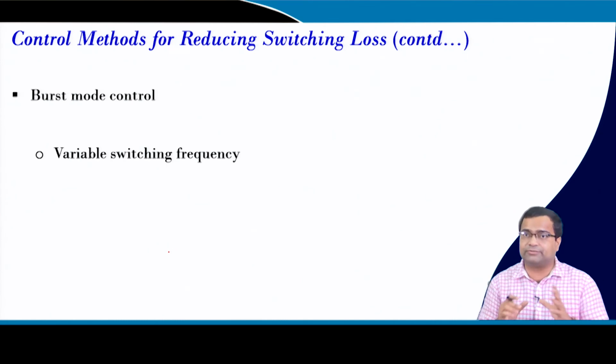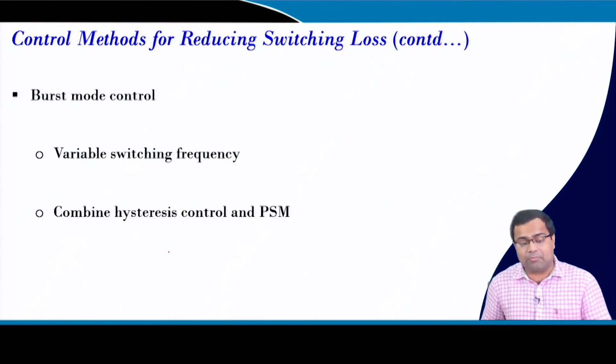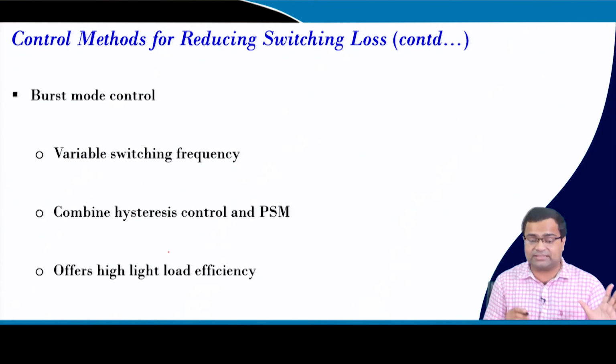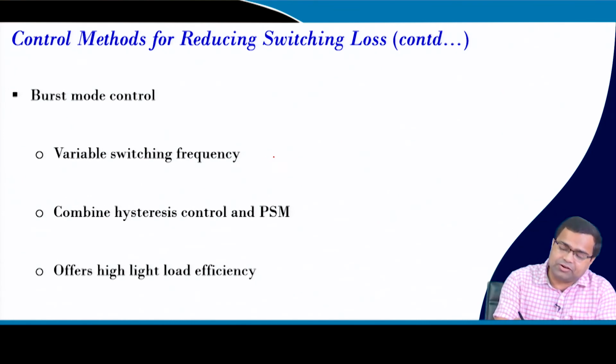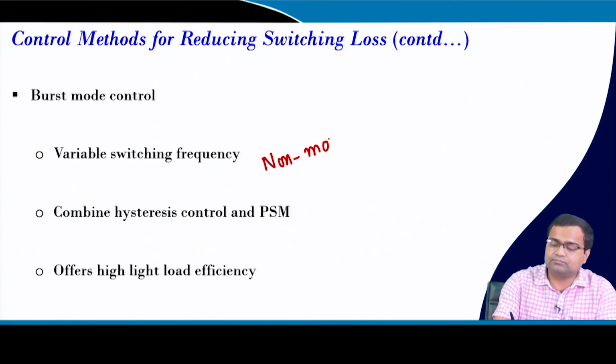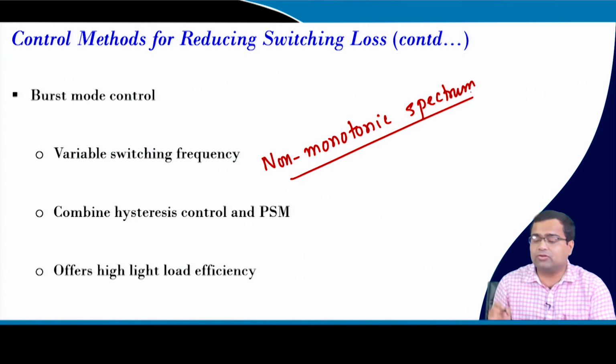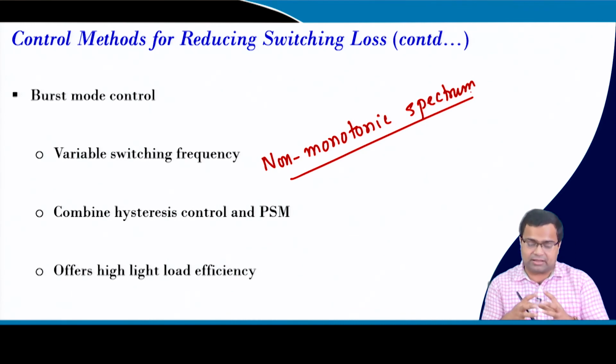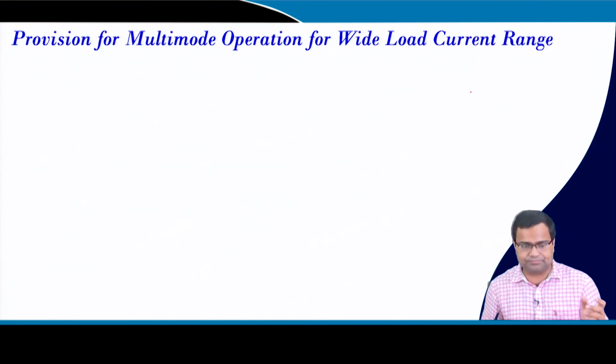The burst mode control is also very popular, it is a variable frequency control, it combines hysteresis and PSM, it offers high light load efficiency. This technique is also non-monotonic, that means the spectrum is non-monotonic. That means in this technique it is very difficult to control the power spectrum. That is why many industries may not prefer it, because of managing the power spectrum, although at low power the spectrum amplitude itself is low, but here the problem is that there can be some non-monotonic behavior in the spectrum that we have seen in the simulation.